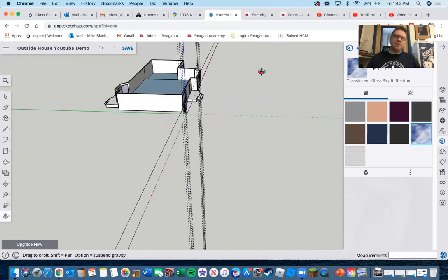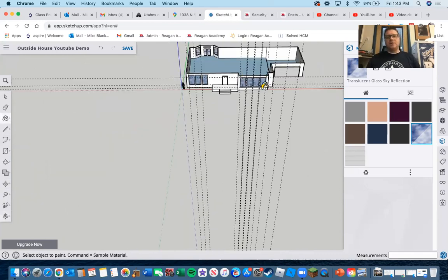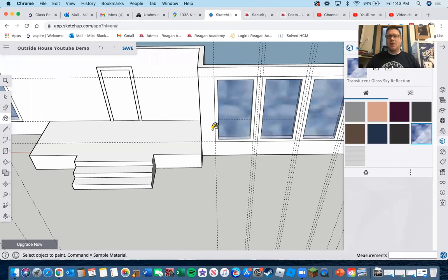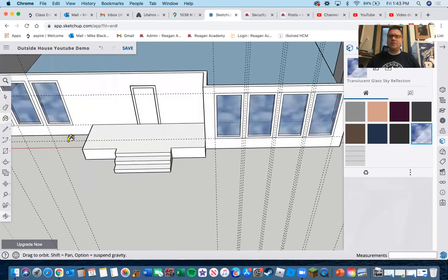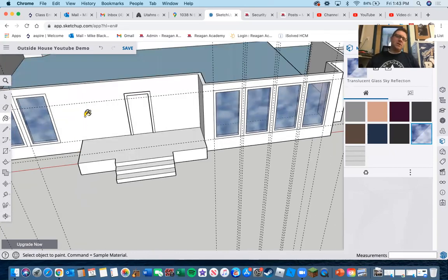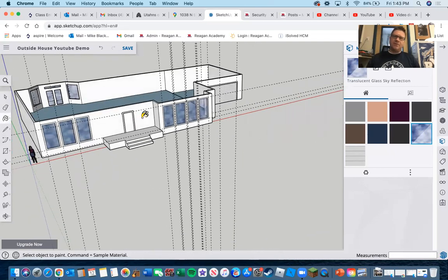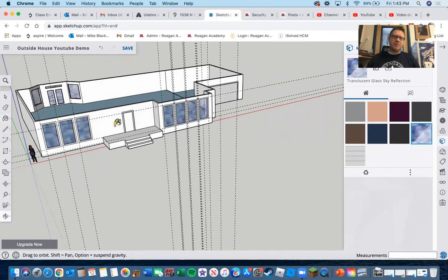There's lots you can do, and lots of different custom sizes. It doesn't really matter how you make them. The biggest thing with Windows is if it's a bedroom, it has to be at least 3 foot by 3 foot, because that is code. In a bedroom, you have to have an escape route in case of a fire. So you need to make it at least 3 foot by 3 foot.